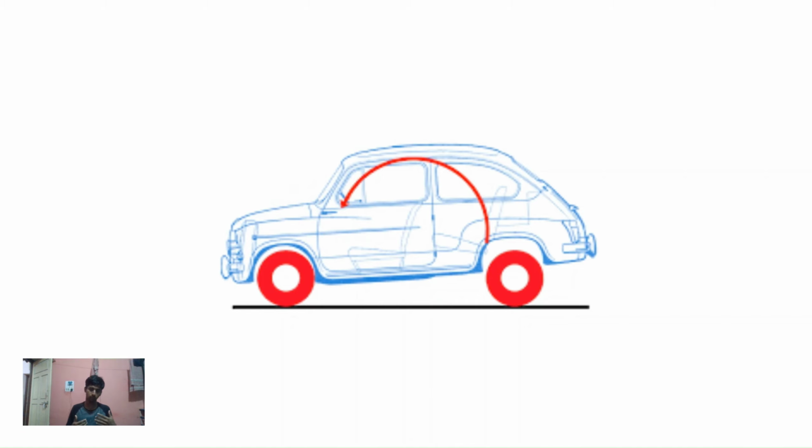And why is that? Because of the longer wheelbase, the turning effect produced by a sudden acceleration or deceleration is counteracted by the normal reactions on both the front and rear tires, and because of that, you don't feel that jerk very immediately. Plus, combined with the fact that you have a suspension, you don't get to see that kind of jerk that often.